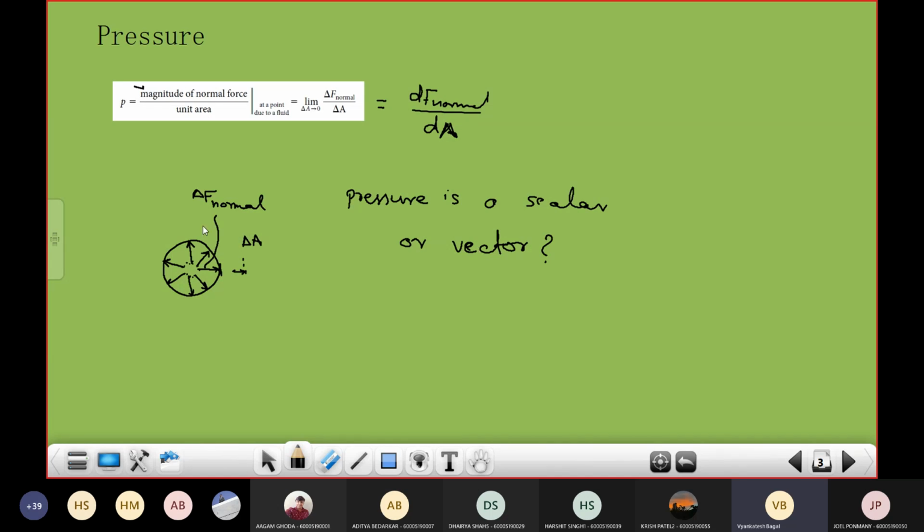See, the air which is inside the ball is creating the pressure distribution, right? And this is equally distributed throughout the inner surface of the ball. So pressure is a scalar, but when it acts on a surface, its effect is a vector, and we call that effect a pressure force.